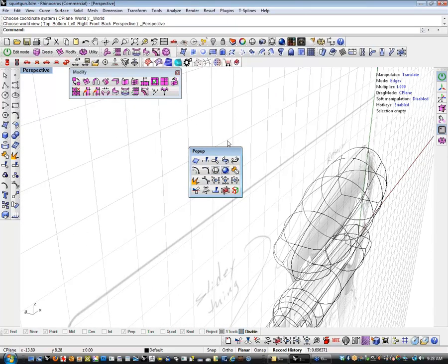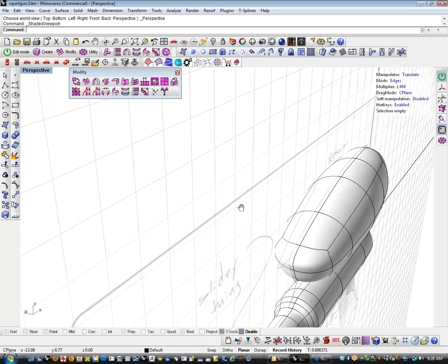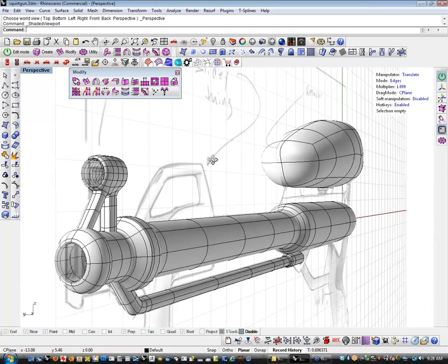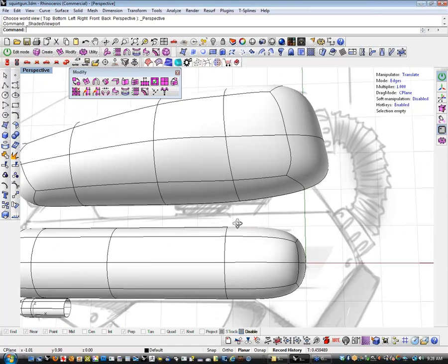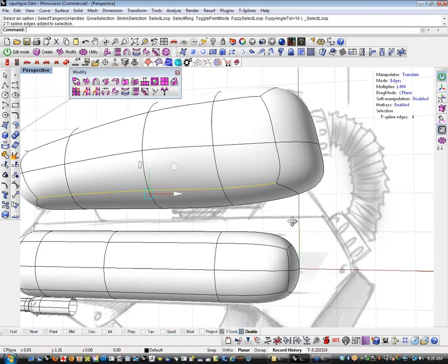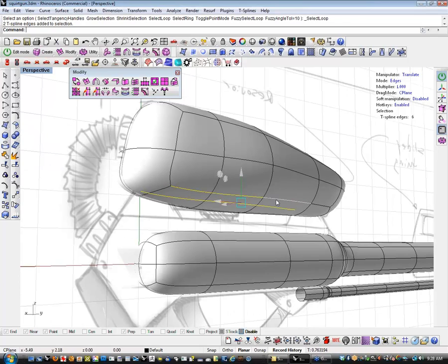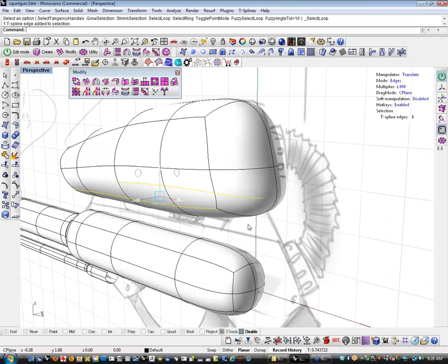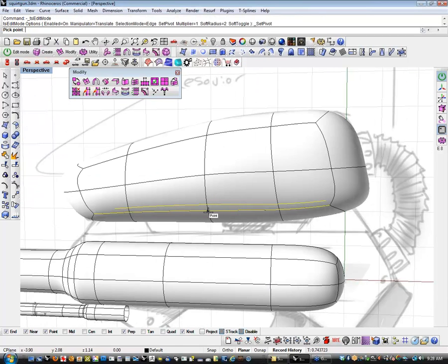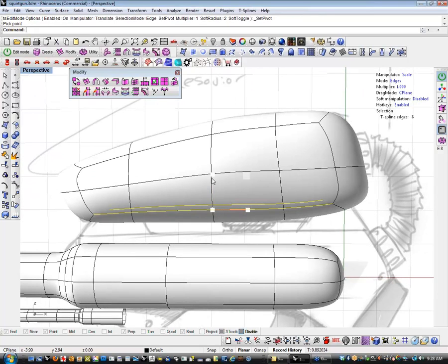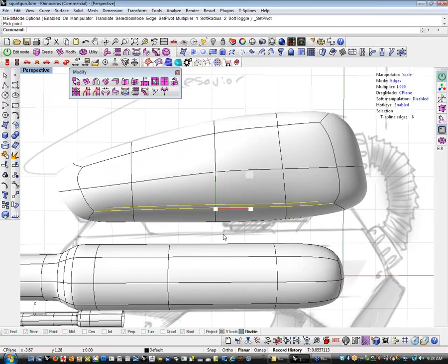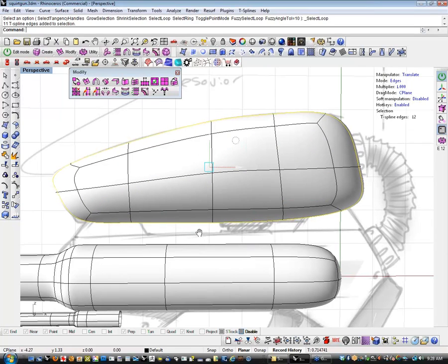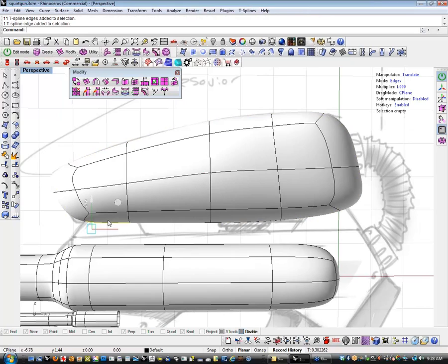In this demo, the emphasis is kind of on speed and how you really want to do things quickly. And in that case, it's much faster to just do a couple of intersecting surfaces and Boolean them together than it is to try and work out everything perfectly in T-Splines. So you could certainly do it, but it's probably not the most efficient use of your time.